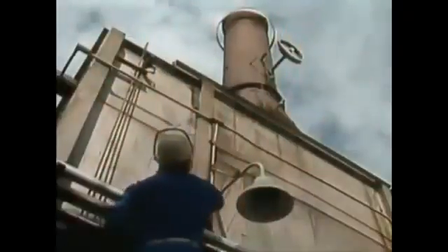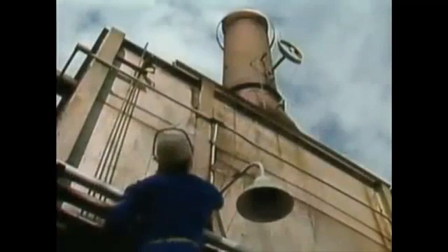Then the stack damper and the burner registers can be adjusted in small increments to meet the desired draft and excess air targets. A sudden rush of air into an air-starved furnace could cause an explosion, since there may be unburned fuel in a hot environment.